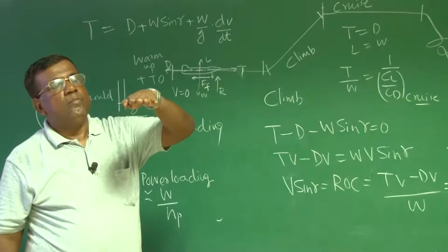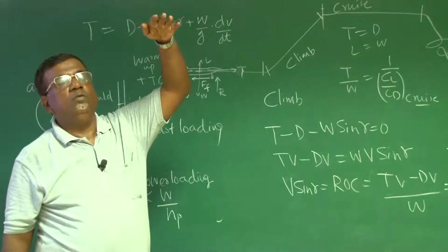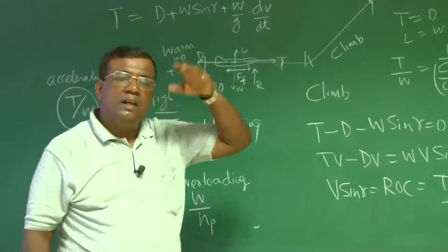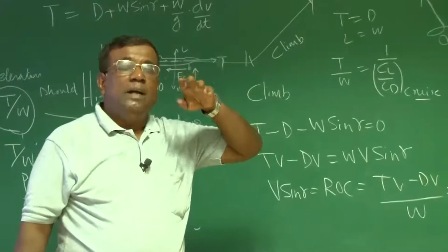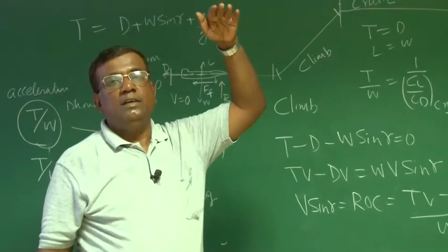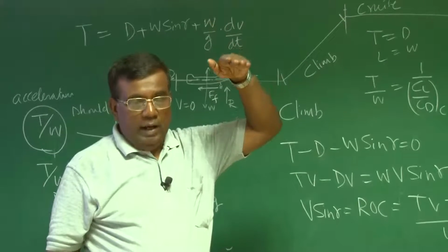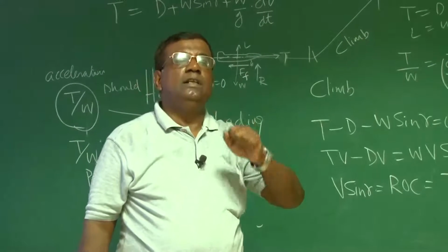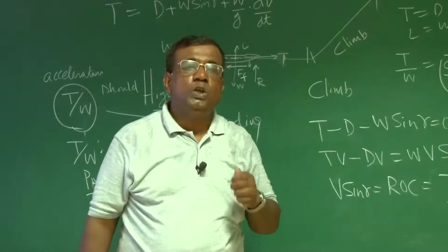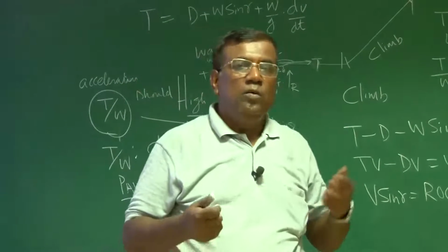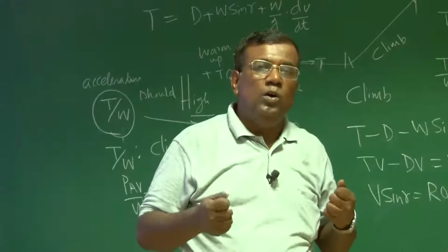But as you go higher and higher, if you want to fly at 300 meters per second, the structural load will reduce because density is reducing. But the reverse, if you are flying at 300 meters per second at 10 kilometers, and if you want to fly at 300 meters per second at sea level, even if your engine gives you power, you have to ensure that now the dynamic pressure has increased, whether the structure will be able to withstand that load or not.